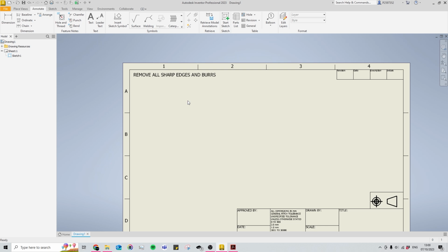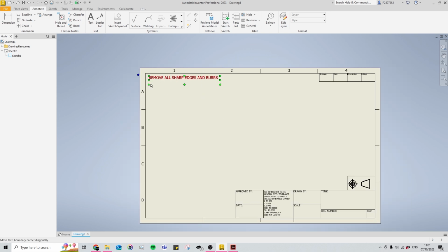The reason I'm doing this is because I create drawings for manufacturers. This note in the corner of your drawing is very useful, as it helps to cover you if someone gets hurt while making something that you've drawn. Adding it directly to the border also means that you don't need to retype it for every drawing you make, saving time. That's also why I've tucked it in at the very top left, because here it's very unlikely we're going to have any of our model views and dimensions that will impede on this area. After adding your note, you should be about done with your border.